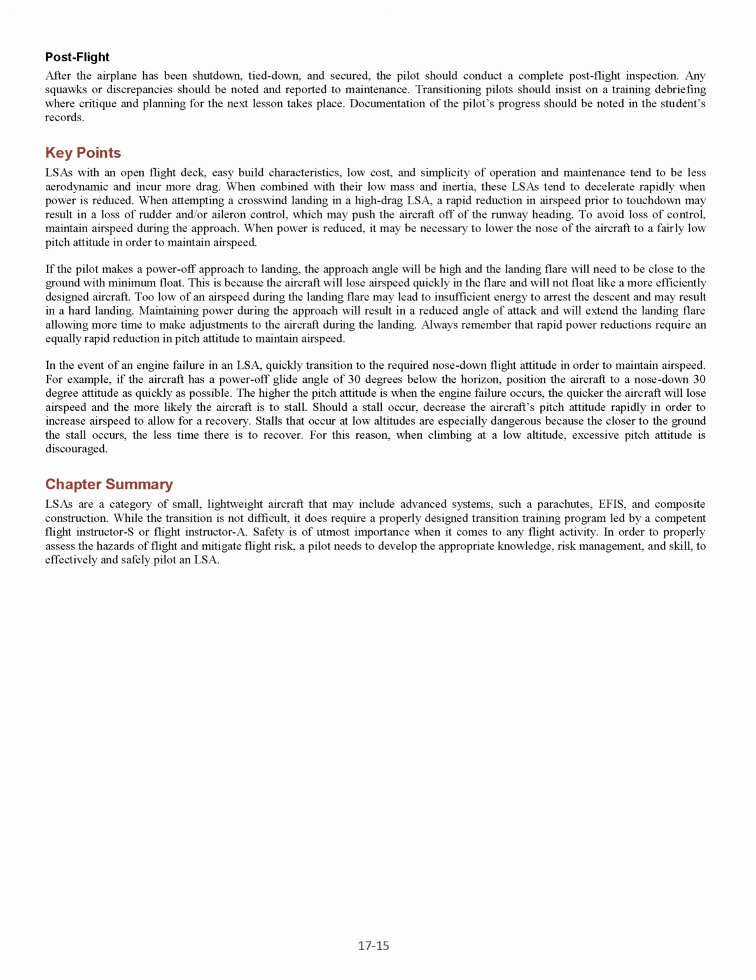Maintaining power during the approach will result in a reduced angle of attack and will extend the landing flare, allowing more time to make adjustments to the aircraft during the landing. Always remember that rapid power reductions require an equally rapid reduction in pitch attitude to maintain airspeed. In the event of an engine failure in an LSA, quickly transition to the required nose-down flight attitude in order to maintain airspeed. For example, if the aircraft has a power-off glide angle of 30 degrees below the horizon, position the aircraft to a nose-down 30-degree attitude as quickly as possible.